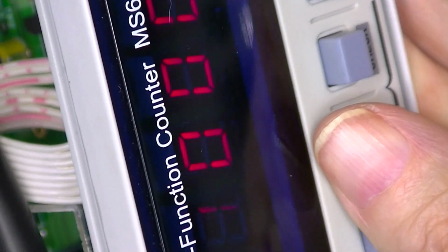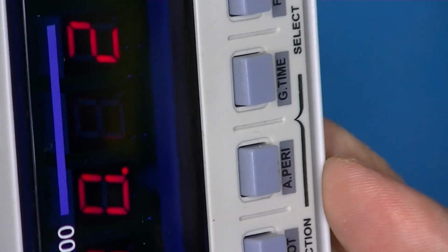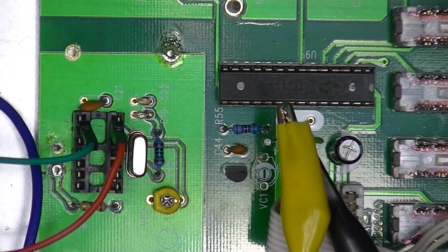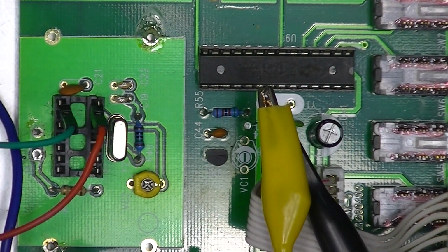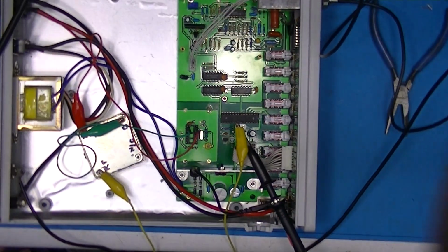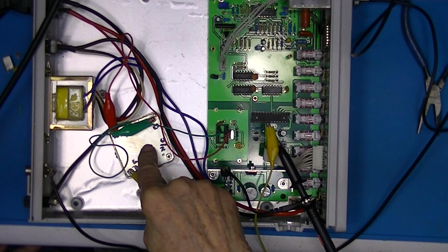I have 10 megahertz coming into the unit. I don't know if you can see that or not, but it's 10,220. So that probably is the fact that the clock is at 7999850 or 855. But it works. So now I need to find a more accurate time base.